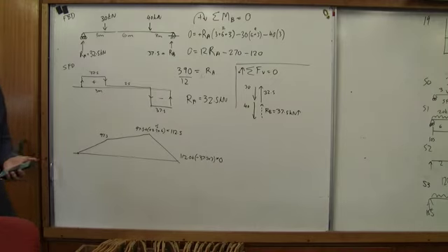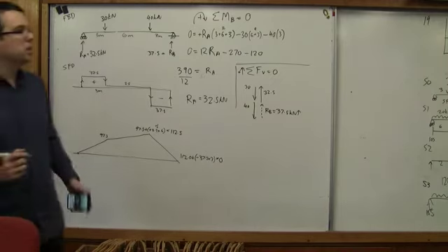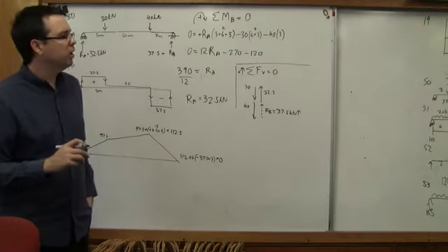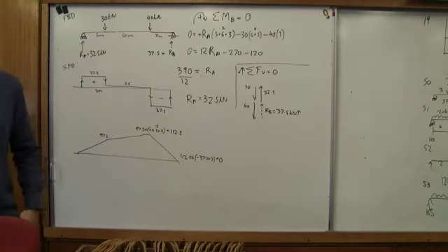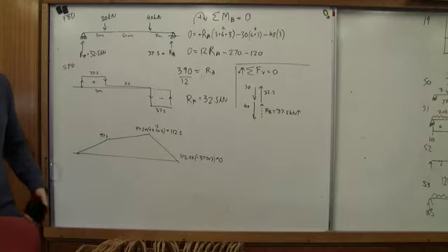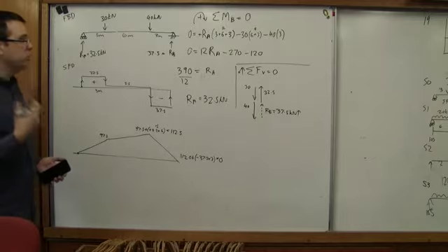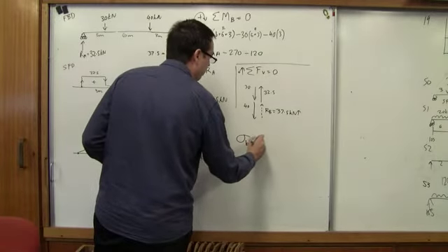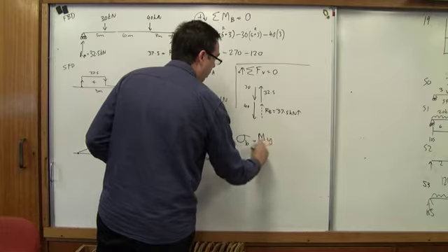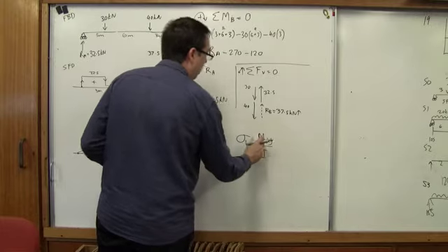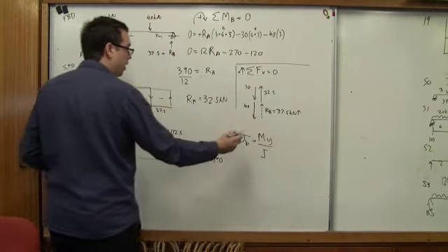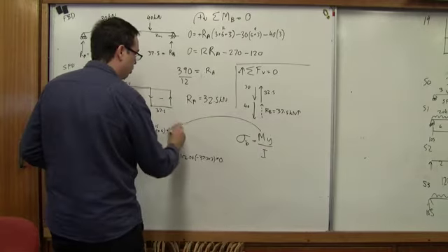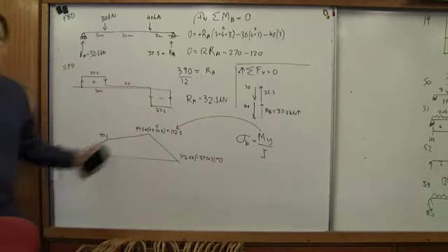Now, does this question ask for anything else? It does. It then says it wants us to figure out, oh no it doesn't, that's it, that's all it wants, right? Bending moment diagram, shear force diagram? Yeah, shear force and bending moment, yeah. Okay, so if we were to calculate a question that asked for bending stress, the value for M times y over I, the value for M that we would use would be that one, because it's the biggest value on the diagram.